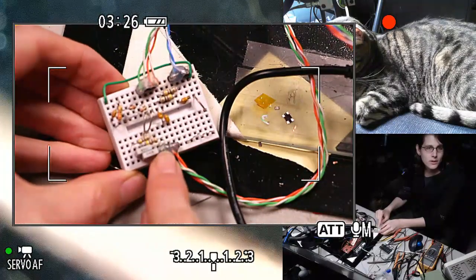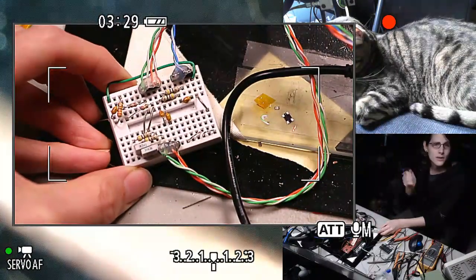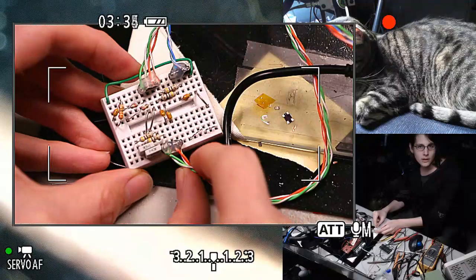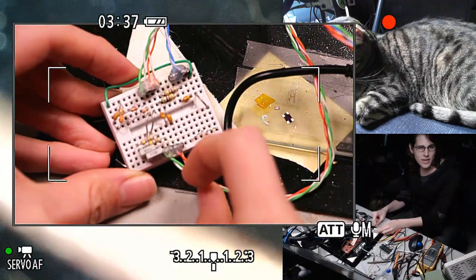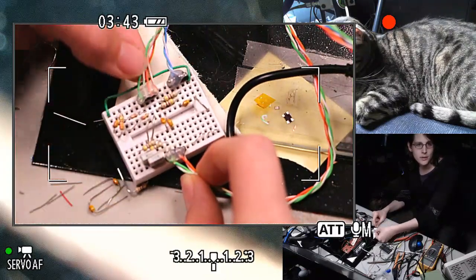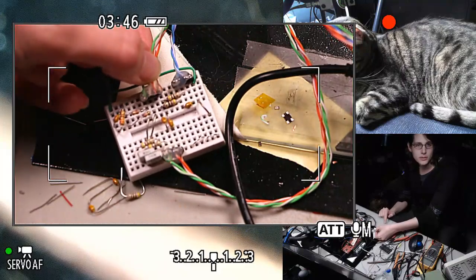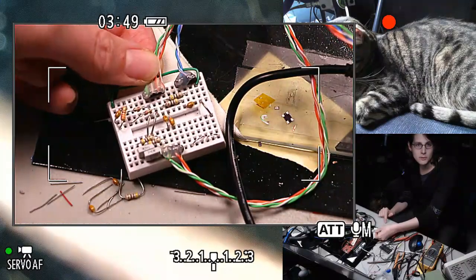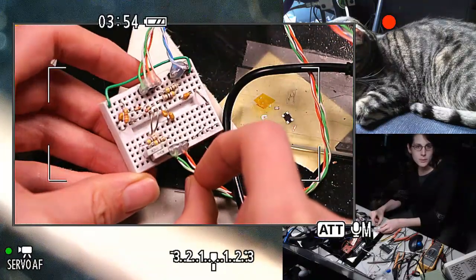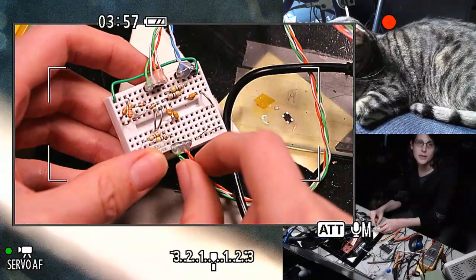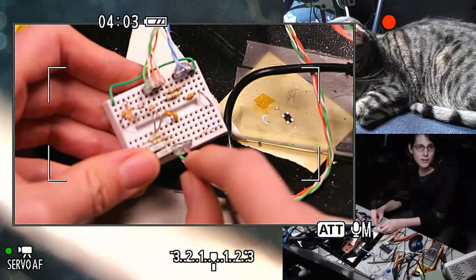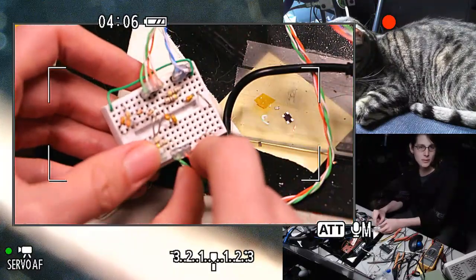This wire here is not quite focusing. There we go. So these two orange and green wires are Ethernet twisted pairs. I think I made these with orange to be transmit and green to be receive on this side up here, and that's the side that goes to this ENC28J60 adapter on the Raspberry Pi. And this side on the bottom, those wires I think are capable of operating in either polarity, so it detects which one is transmit and which one is receive based on which one it gets link integrity pulses on. And those are wired to this eval board with the TI chip.